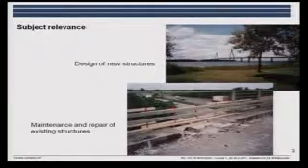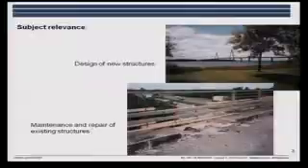repair methods. Could be that you actually, for this edge beam, that's the side of the bridge, which has had a lot of contact with chlorides from de-icing salts, it could be that you chose to use a surface treatment. But if you do that, and you may have ingress of water, you may end up with freeze-thaw problems. And that has actually been experienced.